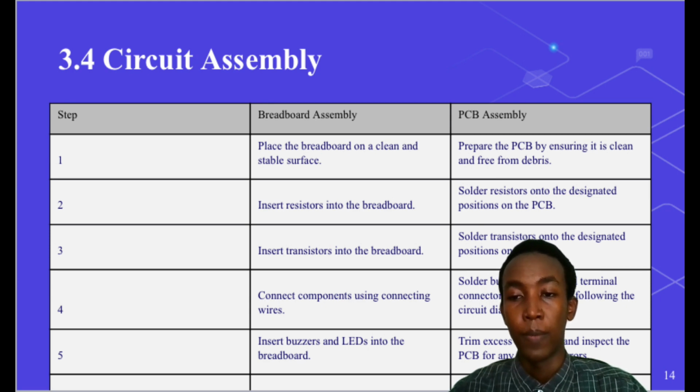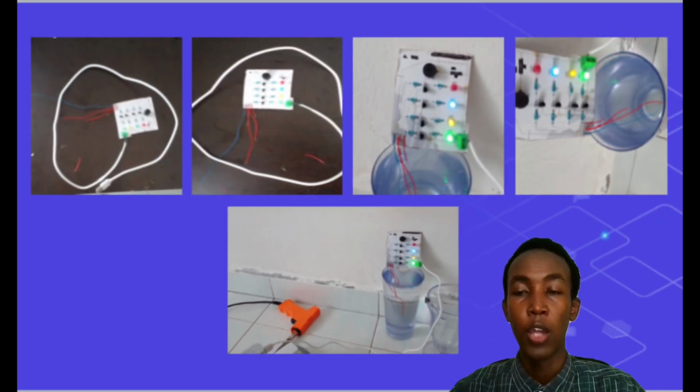And perform continuity and functional tests to verify proper connections and functionality, and finally verify absence of short circuits and errors. And here is the setup we have built after assembling the components onto the PCB layout and connecting it to electricity. And the video is next.